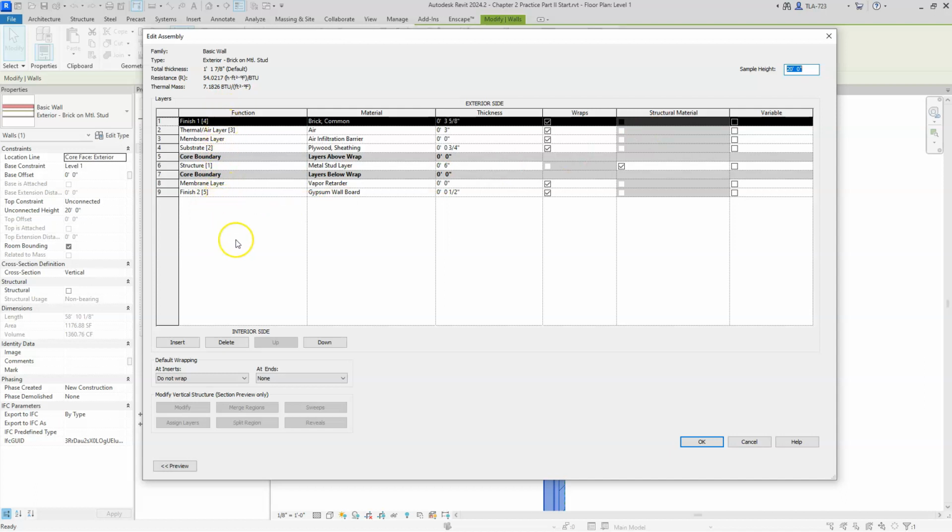and here are all of those various layers that go into that wall. So there are some layers in here that you really can't even see in the floor plan, but they're there because there's a lot of analytical tools within Revit that can detect and verify, for example, how airtight a wall is, how good it's able to resist heat flow and things like that. So we add all the layers whether they're visible or not.